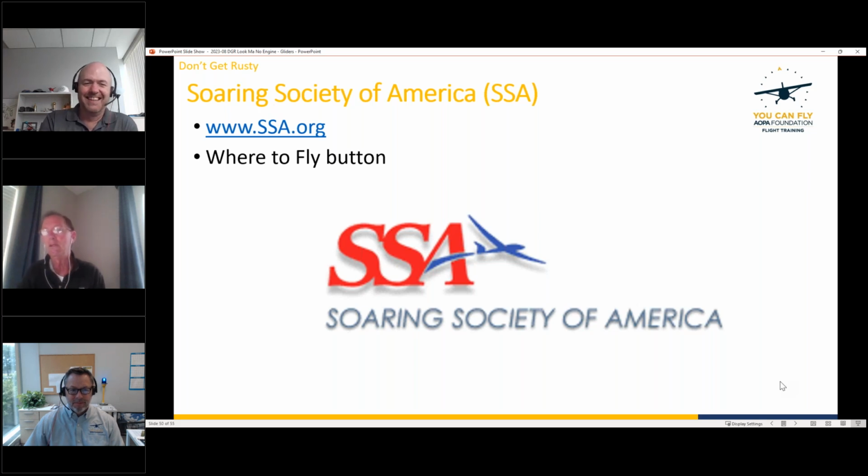With the long wings on the aircraft, it behaves differently than an airplane does, in that you get a lot more adverse yaw from the wings. So rudder is a much bigger part of flying a glider. In fact, I tell people the hardest part of flying the glider is keeping the yaw string, which is your turn coordinator, straight. That is so hard. Yeah, I tell people the only time my yaw string is straight is when it's passing from right to left or vice versa.